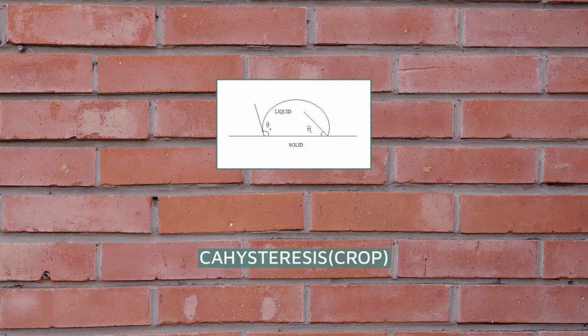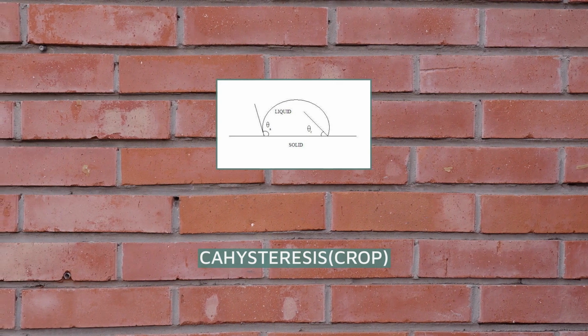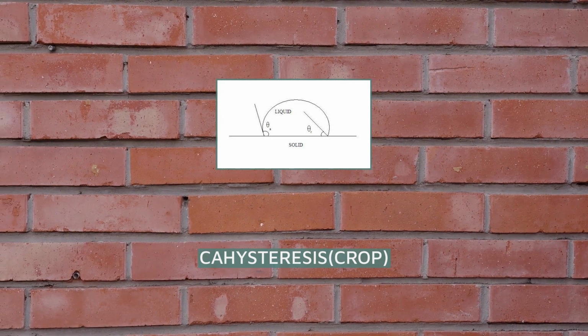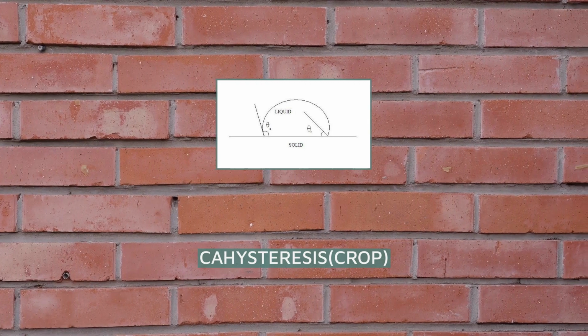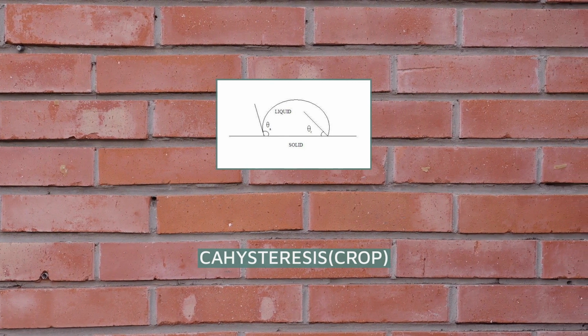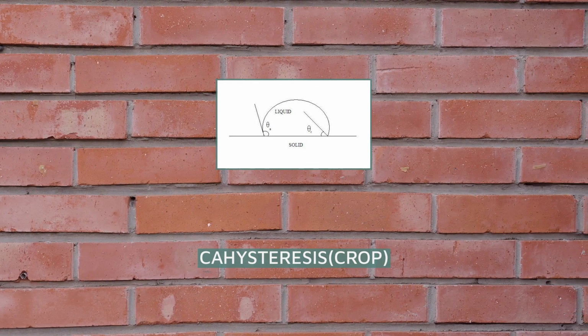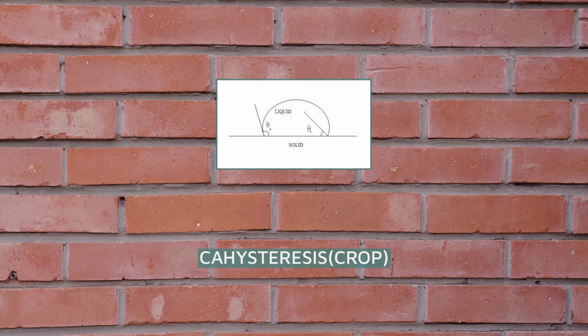When these values are exceeded, the displacement of the contact line, such as the one in Figure 3, will take place by either expansion or retraction of the droplet. Figure 6 depicts the advancing and receding contact angles. The advancing contact angle is the maximum stable angle, whereas the receding contact angle is the minimum stable angle.